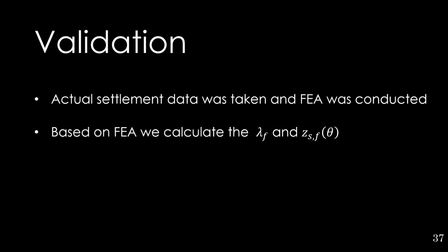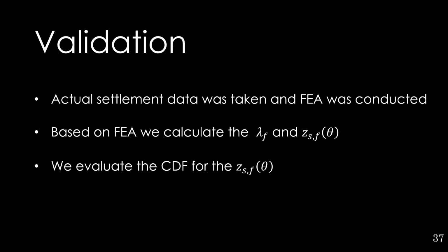Based on the finite element analysis, we obtain the value of failure settlement amplitude and failure settlement profile. For those corresponding values, we calculate the cumulative damage factor, and if the cumulative damage factor at the failure settlement profile turns out to be greater than 1, it means the proposed method indicates the tank has failed, as well as the finite element analysis says the tank has failed.